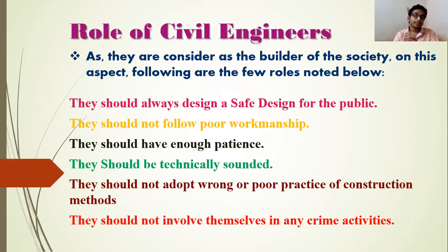galvanic anode cathodic protection, known as the CP method. In that, we introduce an artificial anodic system into a concrete system, either by drilling or when we do some encasing work, to reduce the corrosion. There is a test available to see whether the galvanic anode available in the market is working properly or not, before installing this particular material.